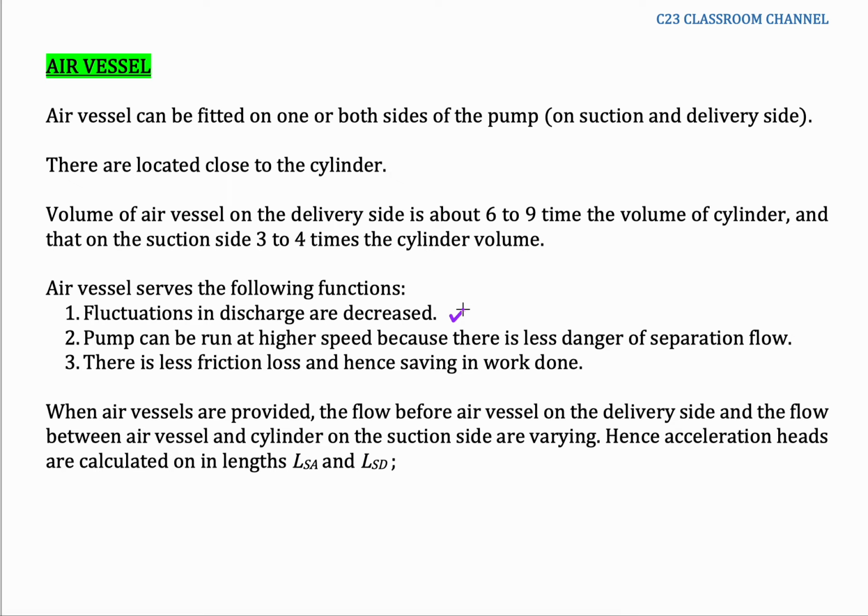When air vessels are provided, the flow before the air vessel on the delivery side and the flow between the air vessel and cylinder on the suction side are varying. Hence, acceleration heads are calculated on the lengths LSA and LSD. So what is the air vessel?